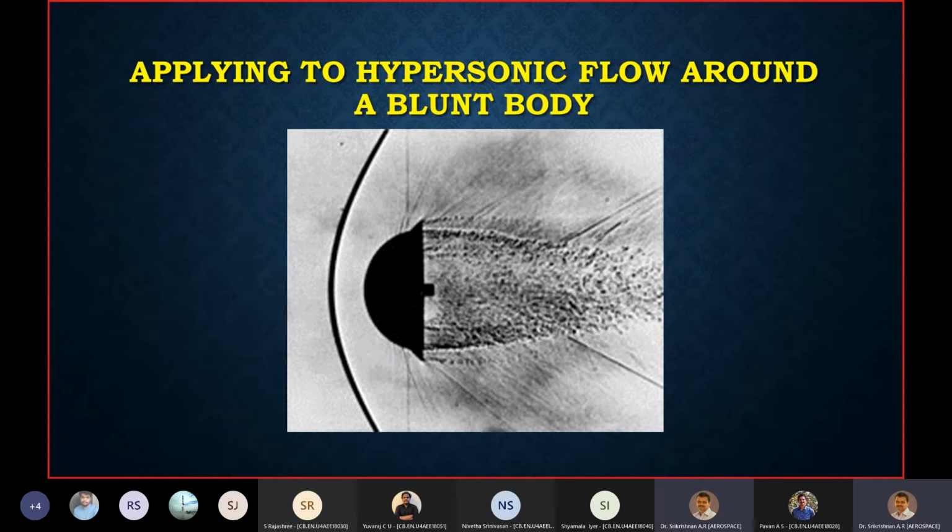Then I'll briefly say where we stand now. We have the governing equations that can be applied to hypersonic flows under the assumption of steady, inviscid conditions, and we are trying to non-dimensionalize the equations. We have defined appropriate terms for each variable so that it can be expressed in non-dimensionalized form. And third, we rewrote the equations using the non-dimensionalized forms. So now we have a series of equations in non-dimensionalized form. In other words, we now have the non-dimensional form of conservation of mass, momentum, and energy as applicable to